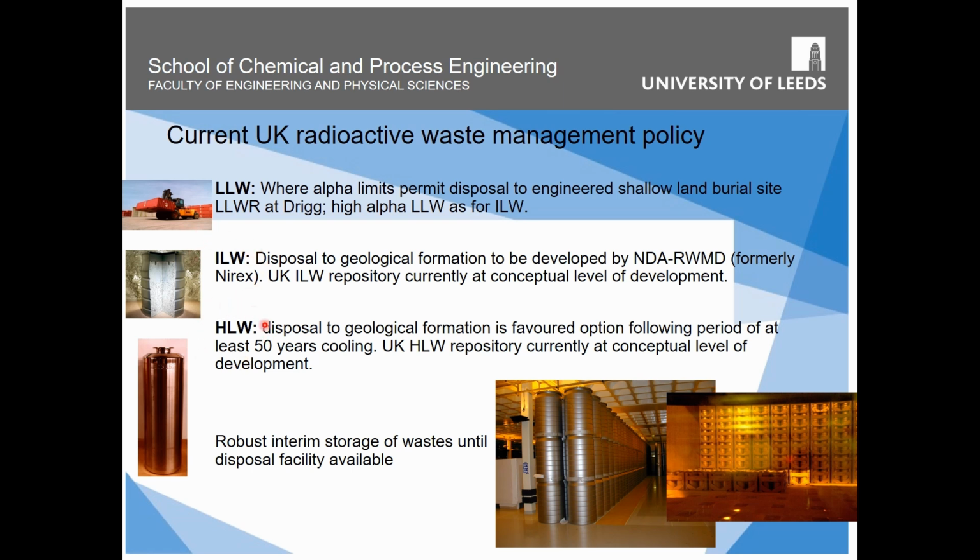and high-level waste, so intermediate level waste and high level waste, we have different means of packaging them. So there's an intermediate level waste container. It's been simulated there, so it's been cut away to show the inside, which is cement. And what we would do is we'd put our waste into that container and backfill it with cement and seal the container, and that container is about 500 litres.